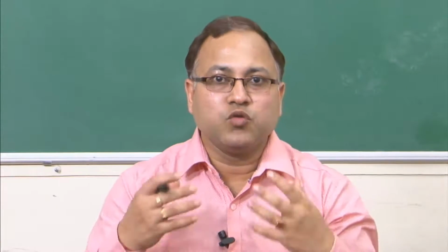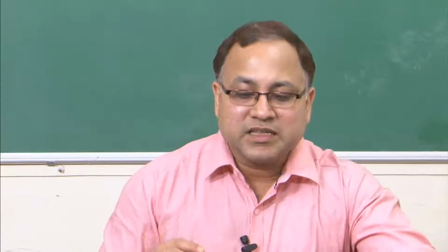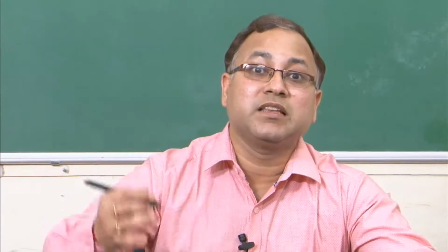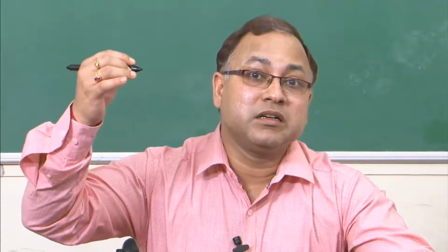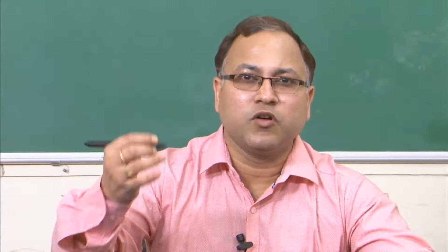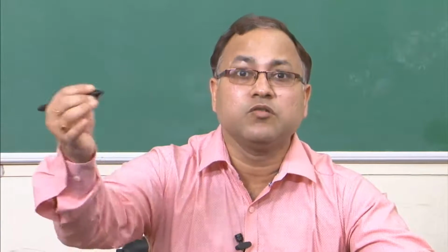So, let us try to first develop or establish the relation, and then we will be plotting them. It is necessary to study the change in void ratio of the specimen with pressure, because that will give you how much change in volume is happening in the matrix. Ultimately you can correlate that with the settlement of the soil, the consolidation settlement, and that is very important for designing any kind of structure, because you want to know how much your foundation will settle due to consolidation.